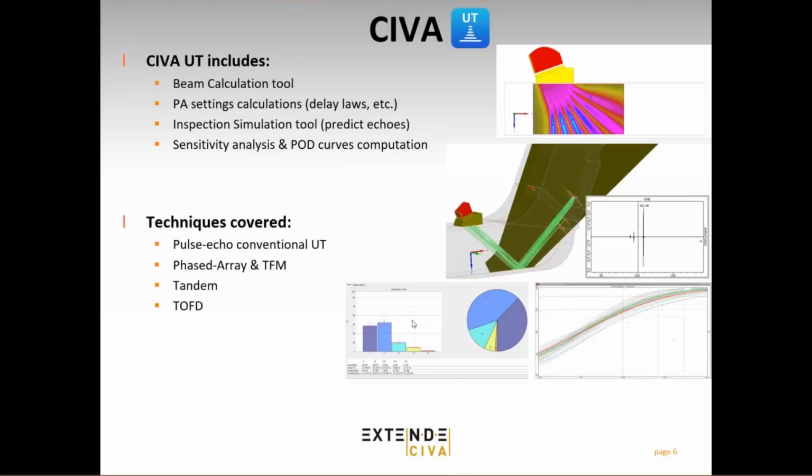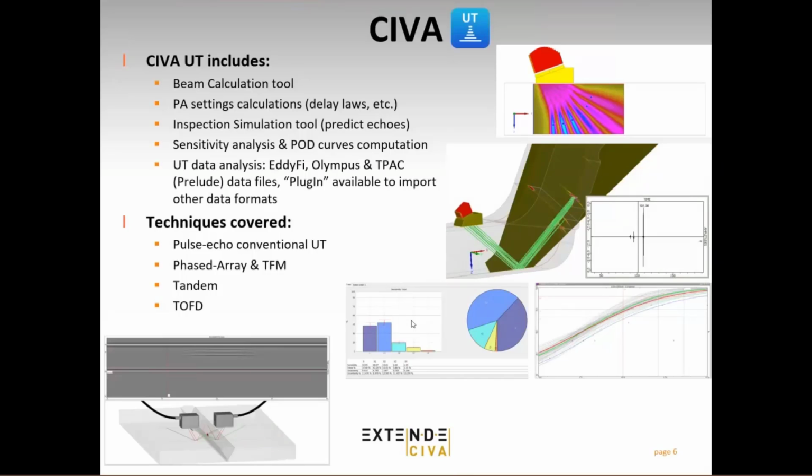pulse echo, phased array, including TFM, tandem, TOFD. Finally, it can also perform UT data analysis by loading real data files, such as Eddyfi, Olympus, and the new one, TPAC Prelude data files, that you can load inside CIVA to perform your analysis within CIVA UT. For other formats, we offer a plugin so that you can develop connections to read your own data files and do analysis within CIVA.